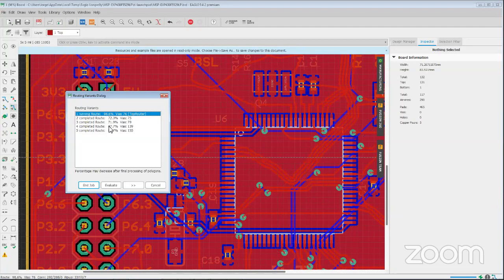If you're not going to do the top router, then my suggestion is set it to a higher effort level. That way you get more variations, and you'll be able to get more options at the end of the Autorouter running.